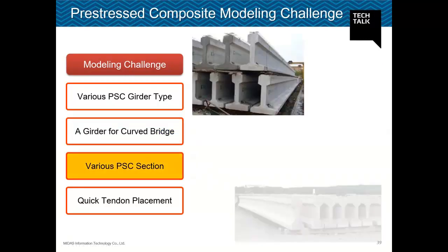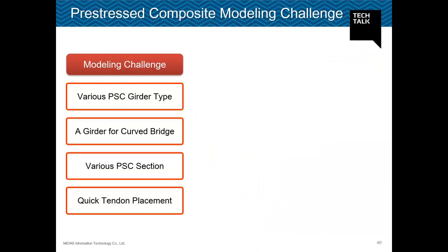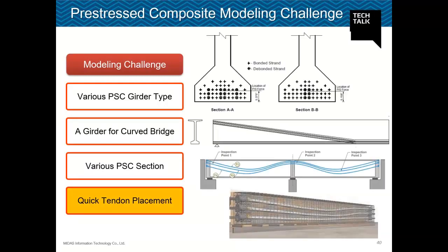Various PSC sections are required. And tendon placement, boy, that is something which is very tedious. Placing the tendons and their profile at the correct location, and then stressing them in different stages.